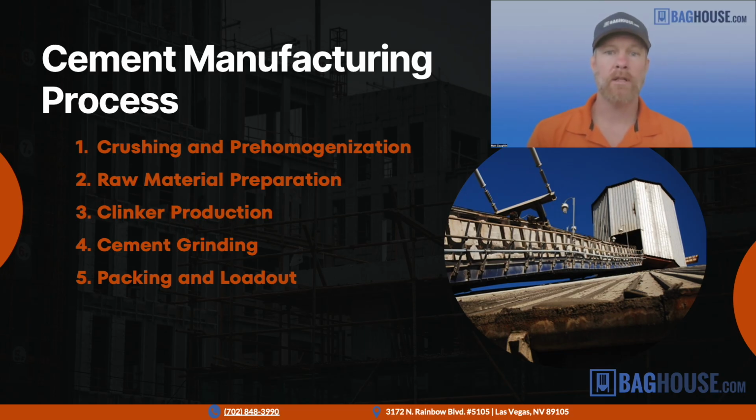So it starts with crushing and pre-homogenization, right? You're taking the limestone rocks and crushing them up, and stacker reclaimer systems may help homogenize materials. So basically just big crusher systems. Then you're going to raw material preparation, where you're grinding this rough material into a raw meal.